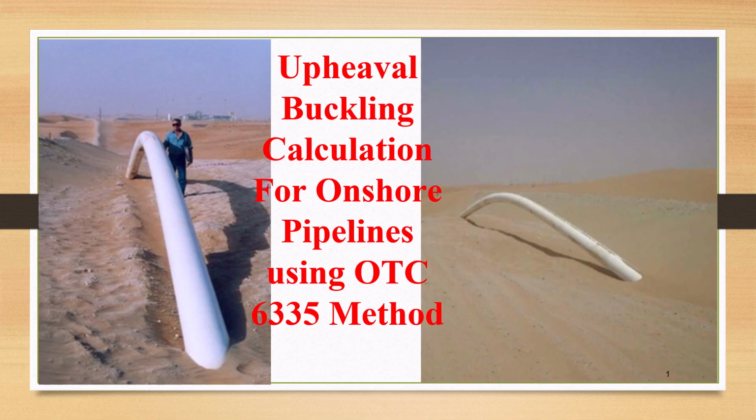Based on the actual depth of cover and the forces generated because of temperature, pressure and other reasons, the pipeline can easily displace that soil cover and come outward, as you can see in these two images. So you will learn the methodologies for performing upheaval buckling calculation using the OTC 6335 method.